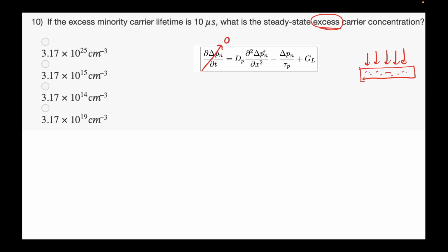You can just assume it to be an n-type semiconductor. We have established that we only talk about the minority charge carriers, so they are holes in this case. Since the holes are uniform throughout, this also does not arise. I am assuming uniform photons, which implies no diffusion.